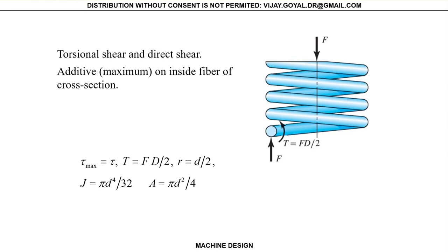Okay, so we want to find what tau we will use in your problem, and I took a small torsional value there, right? Now in the problem, again, just looking at the critical point, it can be here at the corners, right? Because I have shear. It's not the top and the bottom because I don't have a moment. I have a torsion.